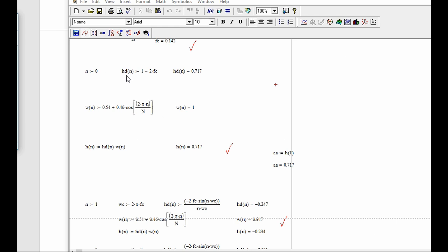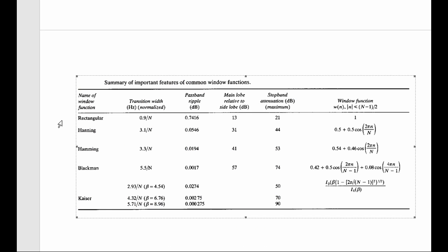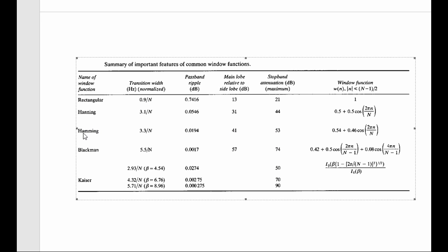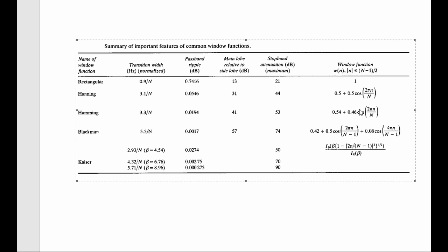So we've got the formula for the low pass filter. The next formula we need is for the windowing function we're going to multiply it with. We decided Hamming, remember, for the quality of it. So we need that formula, cos 2 pi n over that formula there, because we used that one there, but we're now going to use that formula.